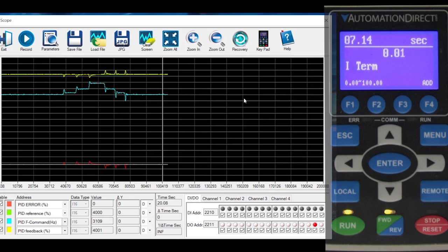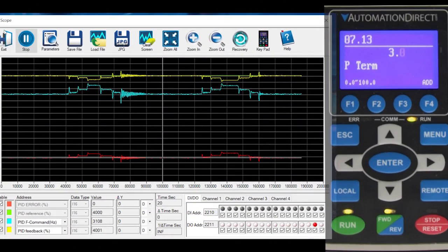Also, with this trial and error method, you usually push your system into oscillation to gauge where you are. In our little pressure demo here, there was no harm in doing that. But many systems can't handle that kind of abuse or might even cause catastrophic failure. So, is there a way to find PID constants that doesn't take the system down for long periods of time and doesn't go into oscillation? Yep, and we'll do that in the next video.